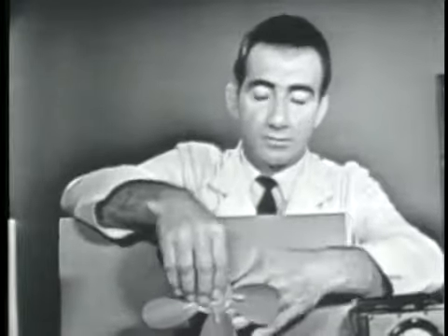And the greater the load on the motor, the greater the slippage. That's right. Now, since we put a load on the motor, this fan, in other words, we've caused the rotor to turn slower. Well, how do we generate enough energy to keep that rotor turning? That's a very good question, Bob, and I hope you've got a good answer. We do. The rotor becomes an electromagnet, right? Right. But how strong an electromagnet is the rotor? How strong should it be? It should be just strong enough to do the job, in this case, to keep the fan blade turning. The strength of the electromagnet is determined by the amount of current that flows through the conductors of the rotor. The more current, the stronger the magnet, and so therefore the current in the rotor is determined by induction.